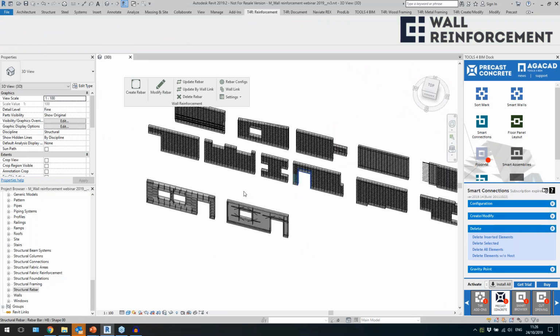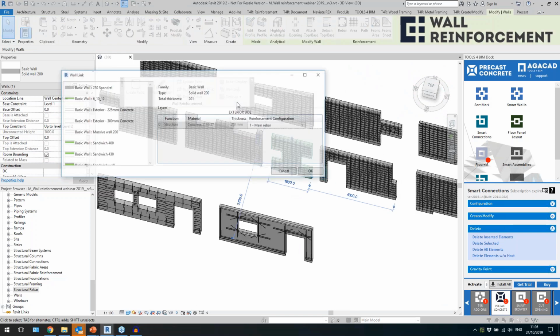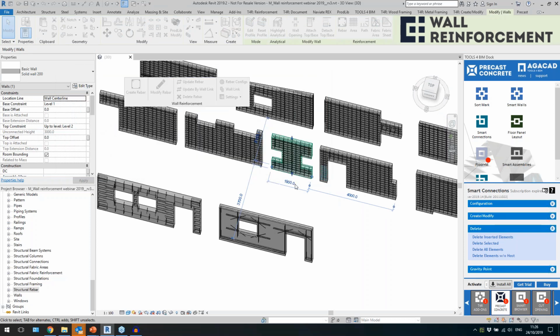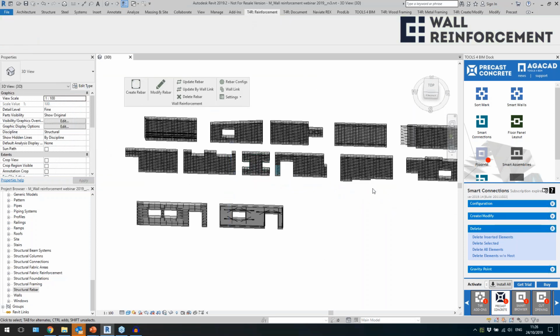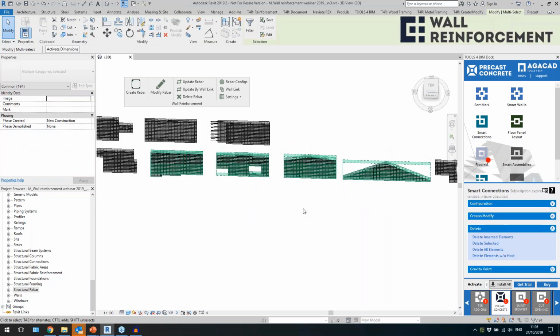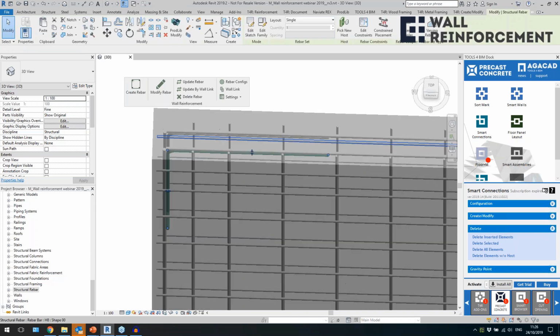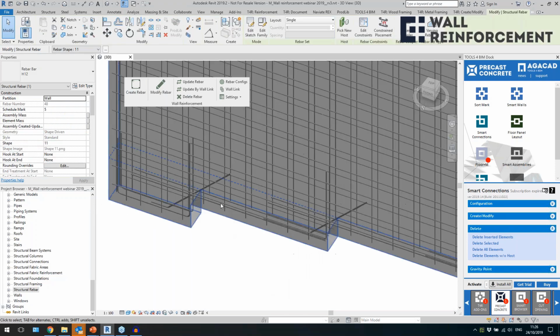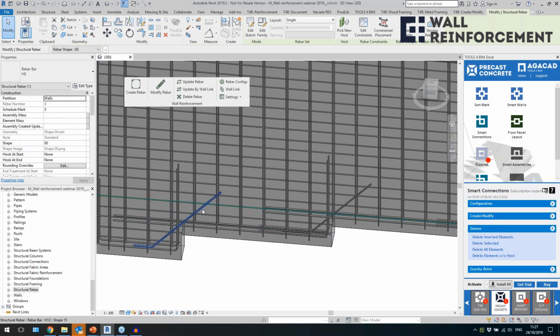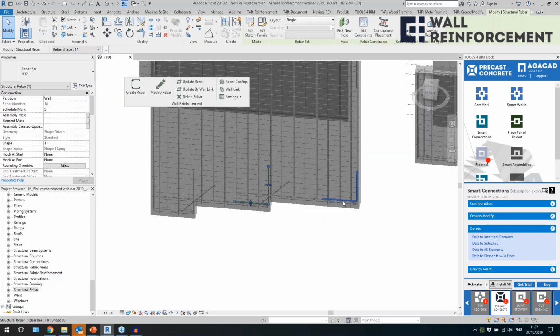Now when you apply one of the configurations, actually you can go ahead and say that now I want to use another configuration, for example this one, right? Or maybe, which should be more interesting, we'll select these walls and create reinforcement now for these. So you see I select all the rebars and windows, doesn't matter, it will filter out walls. And now it just generated these perimeter bars, right? So we have this diagonal bar created because of these changes. We have these bars over here created.